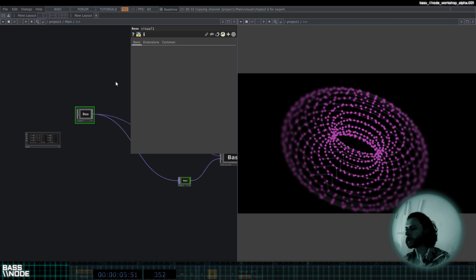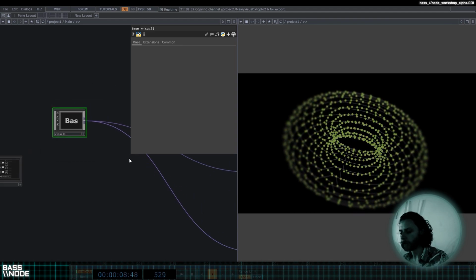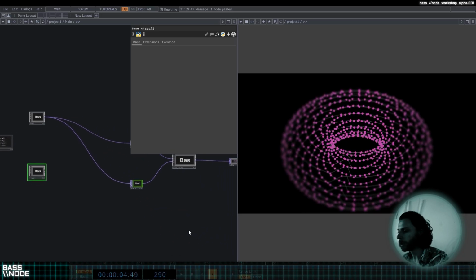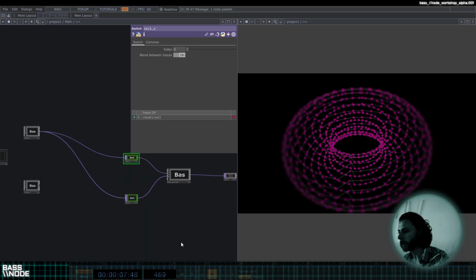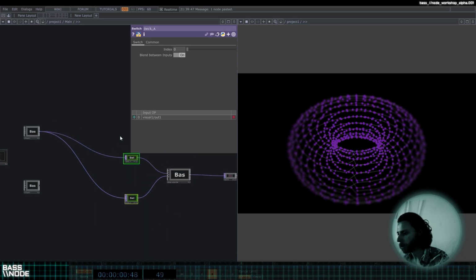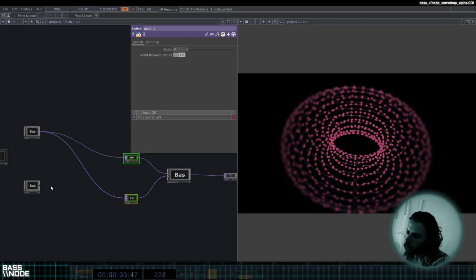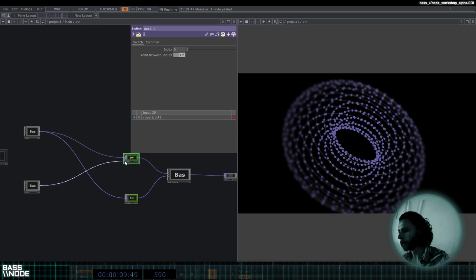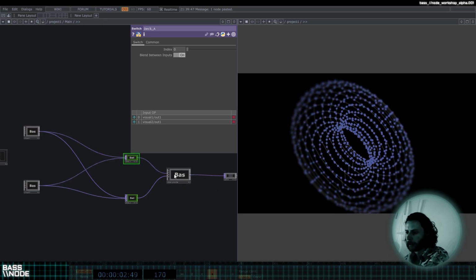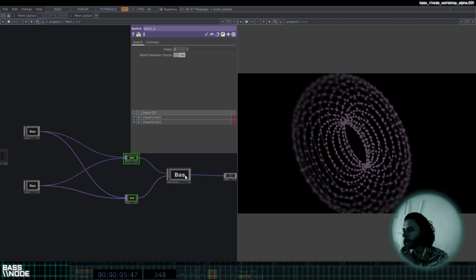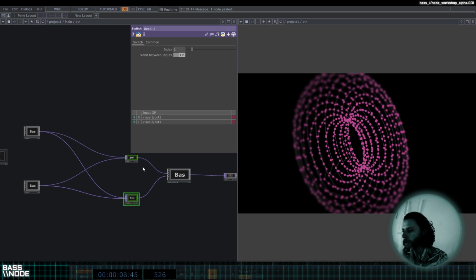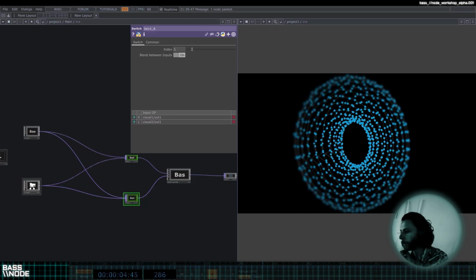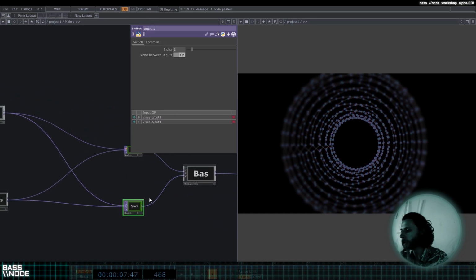So we're gonna just copy and paste this entire visual one. So Control-C, Control-V, and we're gonna take this and put it into the 2 switches I have here. So if you highlight both of these by right-clicking and dragging, or shift-clicking, and then clicking and dragging from our out into either one, it'll bring it into both. And this is just a simple mixer component I built for you guys. And if you look at this, switch 1 is gonna be 0, and switch 2 is at 1. So that means our second input is toggled in our second switch.